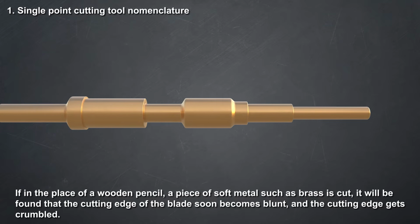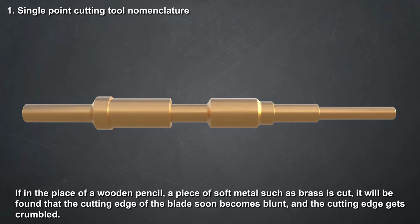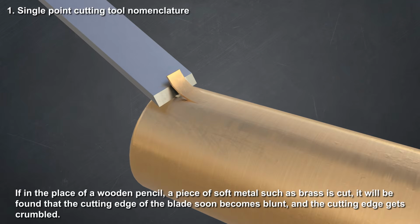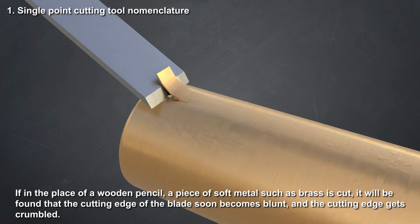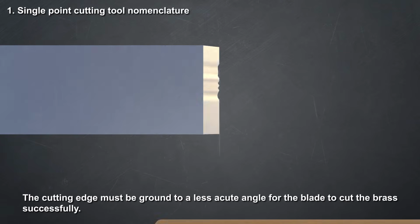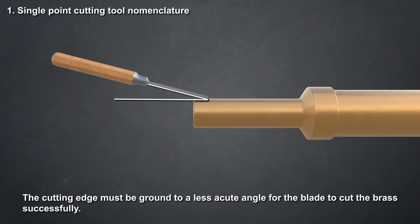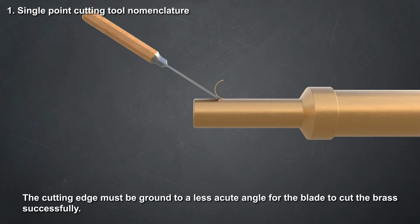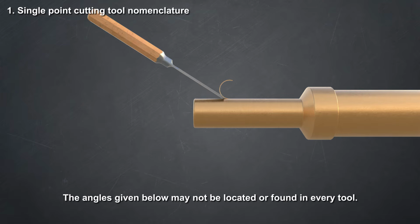If in the place of a wooden pencil, a piece of soft metal such as brass is cut, it will be found that the cutting edge of the blade soon becomes blunt and the cutting edge gets crumbled. The cutting edge must be ground to a less acute angle for the blade to cut the brass successfully. The angles given below may not be found in every tool.